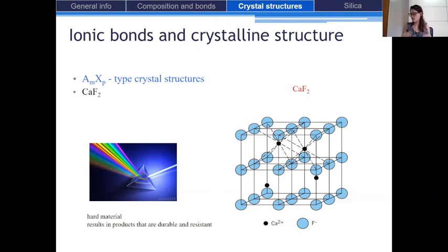It is the case of calcium fluoride, where we have 2 fluoride for 1 calcium. So applying the second rule, you will find that the radius ratio will be about 0.8. And looking at the table we presented, the coordination number is 8, which means that you have a cubic geometry.